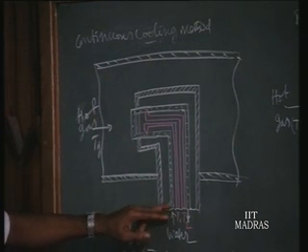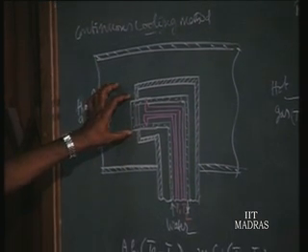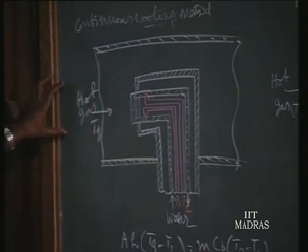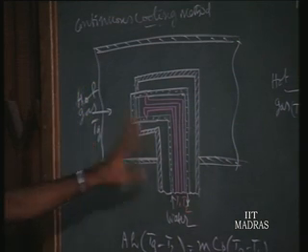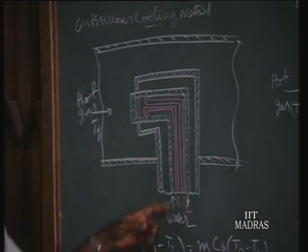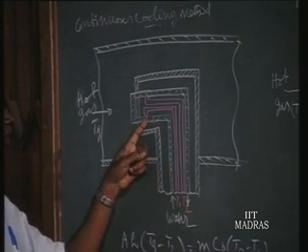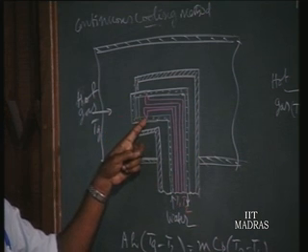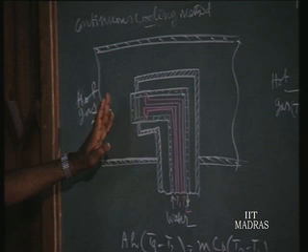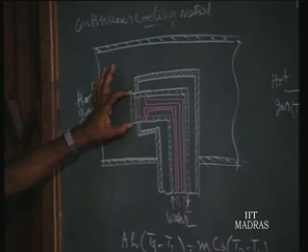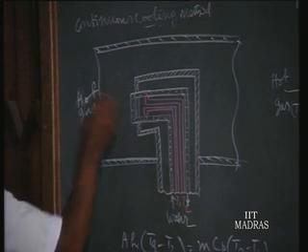We have a pipeline carrying water, part of whose passage is exposed to the hot gas coming in. This hot gas temperature Tg is very large. It may melt the thermocouple wire. So what is done is the thermocouple wire is used to measure the inlet water temperature, just before entry. Later the hot gas transmits the heat to the water in this cylindrical area, say area A, through which heat is flowing into the water.